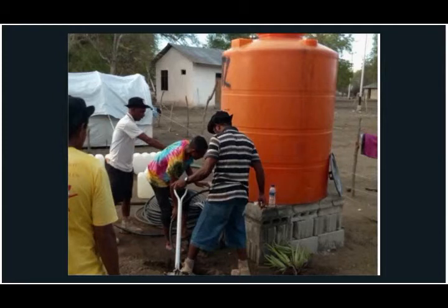So it raises the importance of having information on the area you are going to, by secondary data, by hydrogeology reports, existing networks, existing boreholes, the depth, the size, the yield. So all the information you can collect will also help you with the decision. And for sure, all that Samuel mentioned will not necessarily be what you will do in the first week of your arrival in the situation.